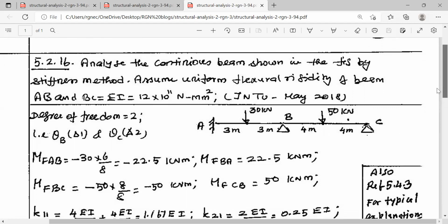Now the given beam is treated on par with a fixed beam at all the supports with fixity. Then we are deriving the given beam by adding the impact of the moments caused by the rotations theta B and theta C. That is the approach followed. So the fixed moments are calculated. Then for calculation of the moments caused by the rotations, we are calculating the moment caused by unit rotation at B and C. And the moment caused by unit rotation is multiplied by theta B and theta C